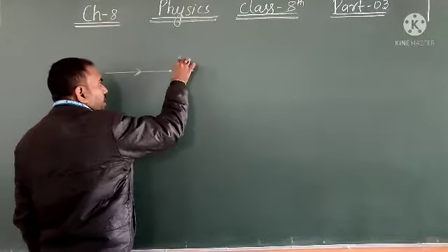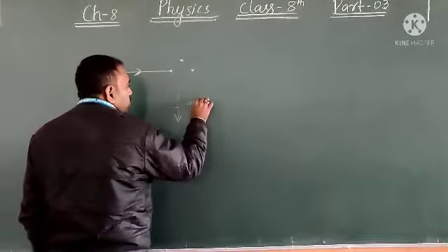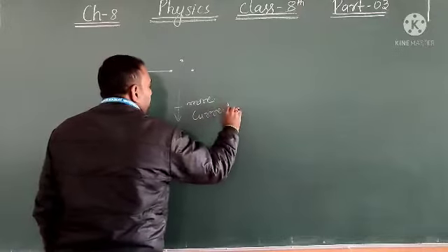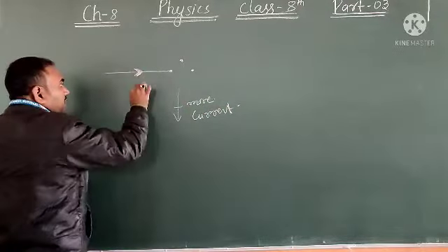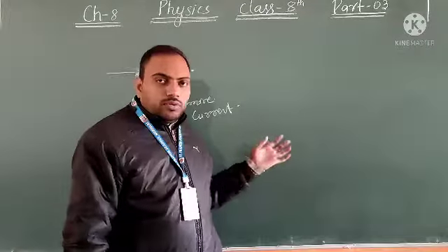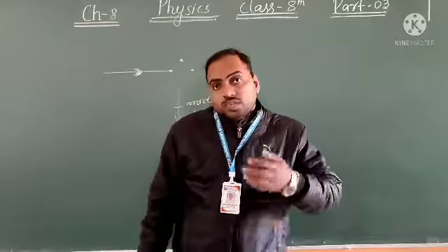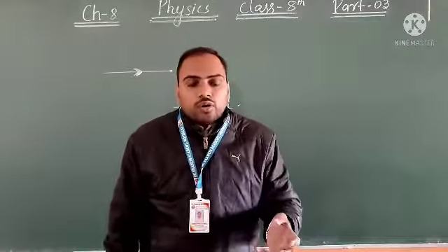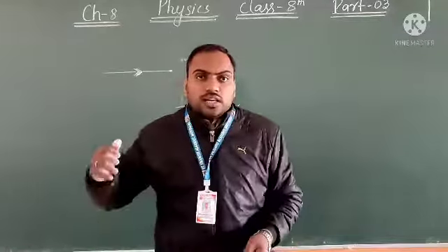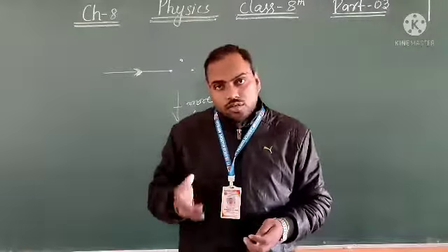If you add your iron, it will draw high, more current, that your circuit is not able to load. If you added it and your circuit is not able to load it, this phenomenon is called overloading. Excess current flows through the circuit and that circuit is not designed for that much current.